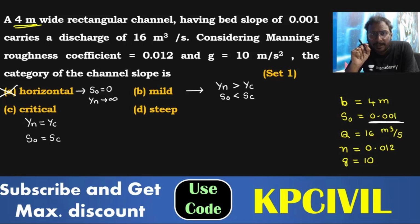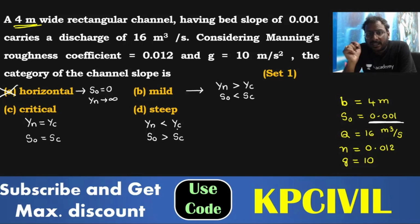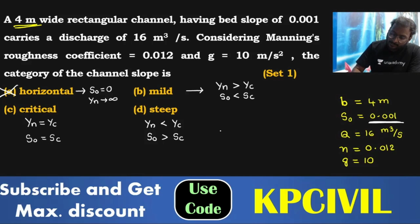Last one, steep sloping surface. For a steep sloping surface, normal depth less than critical depth, S naught greater than Sc. So if you prove any one condition, your question is completed. From the given data, if you prove any one condition, your question is easily completed. For it, what do you need first? Critical depth Yc is needed first for any condition.